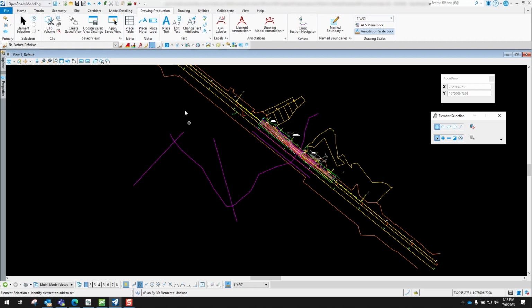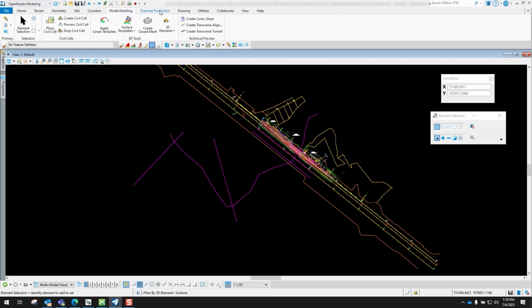So to do that, there's a tool underneath here, underneath the modeling detailing and underneath the 3D elements, because whenever survey goes out there and picks out that valley section and also that stream bed profile, they have certain points that they've created, and it's a 3D element, and we're going to convert those into a 2D element for an alignment, and then we can assign the profile to it.